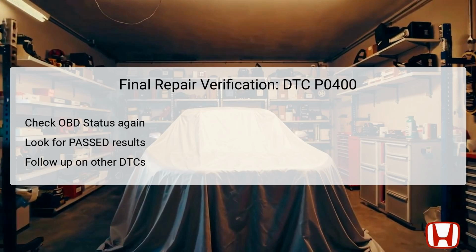corrections. If the status indicates not completed, further inspection is necessary to determine the cause and to recheck OBD status again. It's paramount to ensure that there are no other pending or confirmed DTCs indicated. If additional codes appear, these must be addressed through respective troubleshooting instructions. This systematic approach assures that issues are thoroughly examined and